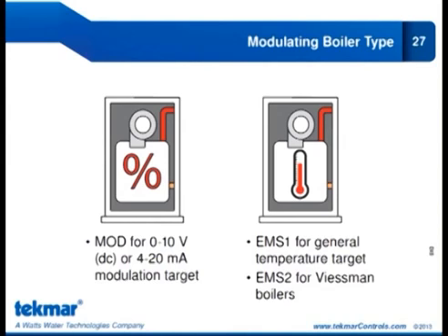So again, you may have a modulating target temperature boiler, such as a Vitodens, with a direct drive capable control, such as the Lochinvar Sync, and then just a standard conventional 2-stage boiler, copper fin 2 Lochinvar, or even a single stage cast iron. So you have a myriad of applications. It's very flexible how you can operate this plant.